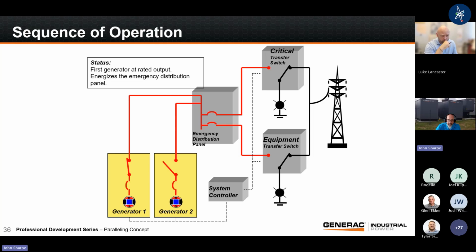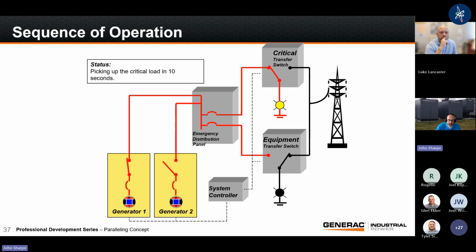Once I energize the bus, again, notice that I am energized to source 2 on both transfer switches, as well as to the load side on generator number 2. So once this switch throws over, this switch sees that I'm available and says, okay, I got a perfectly good source. It's going to switch over to source 2. However, we have the second switch.